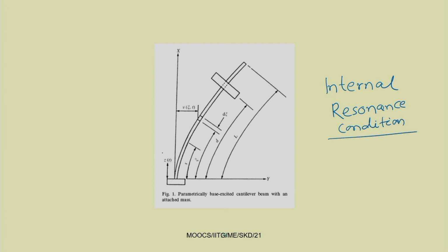The cantilever is moving up and down. When it is moving up and down, due to slenderness, this beam moves in the transverse direction. If we take this angle as phi, you can see that this sin phi can be retained. If we take this distance s, it can be retained as dV by ds. So sin phi will be equal to dV by ds. From that the term cos phi can be obtained, and one can write the moment.